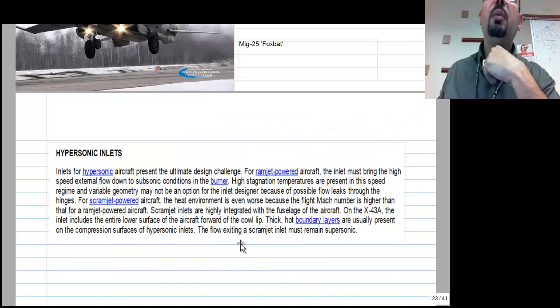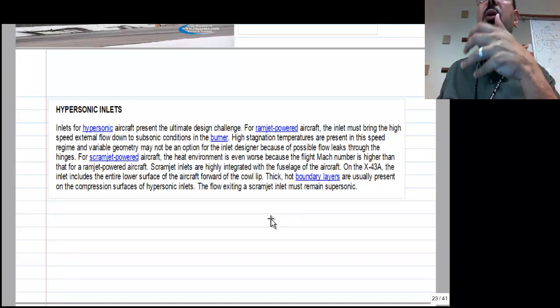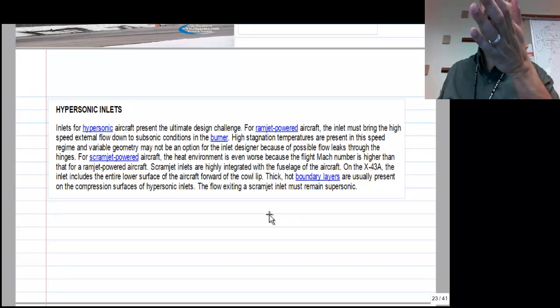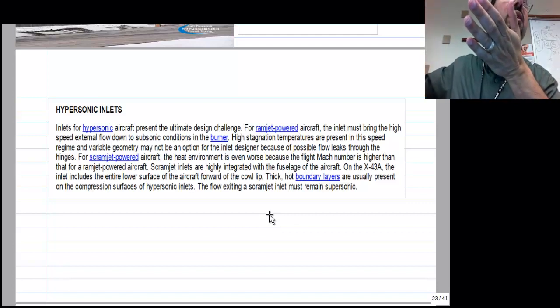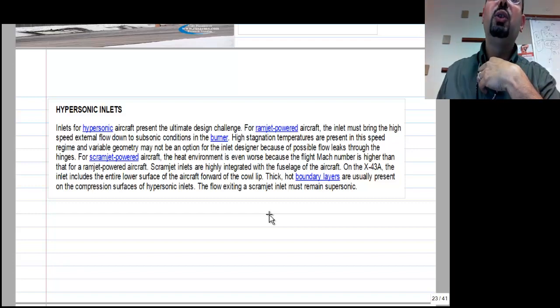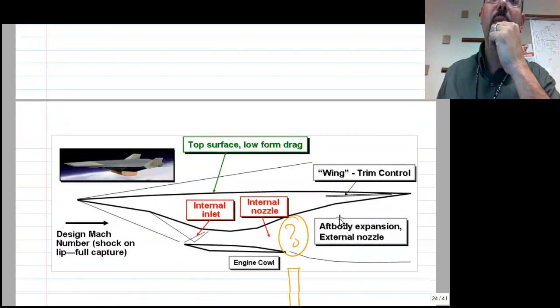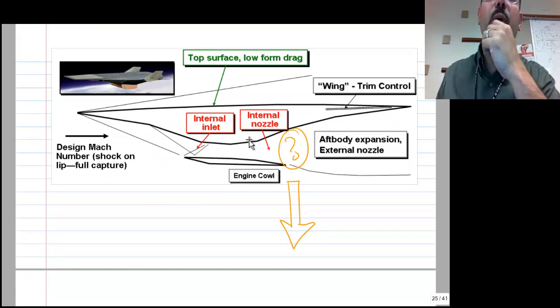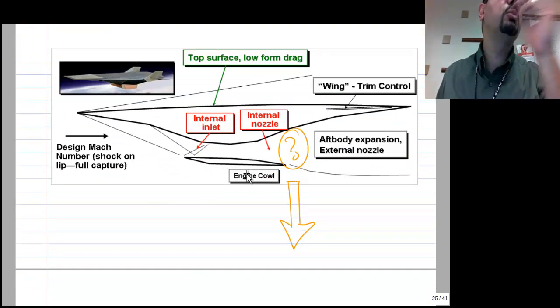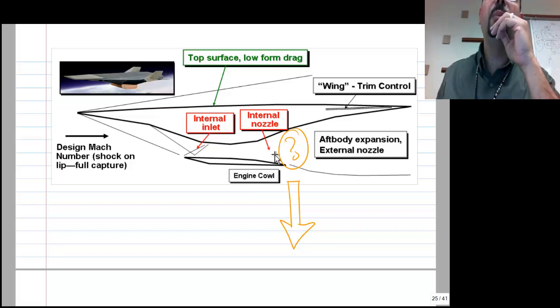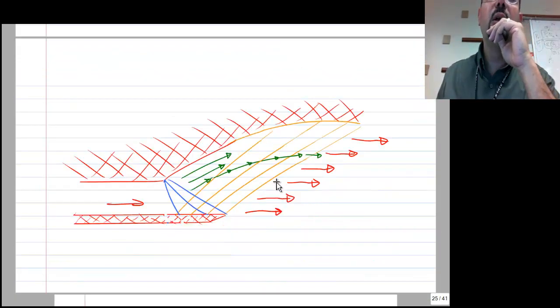And he's saying here that for the hypersonic inlet, you not only want to absorb the shock, but you also want to increase the pressure inside, so that you don't have to use a compressor. Alright? And now, we will talk about the combustion inside in chapters 9 and 10 next time. But let's look at what happens after the combustion, in the expansion.